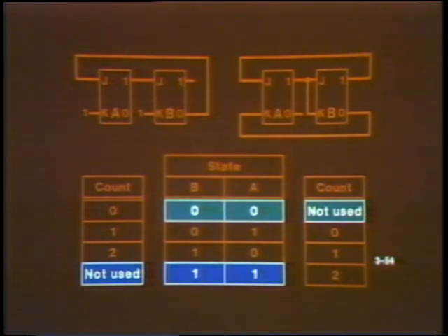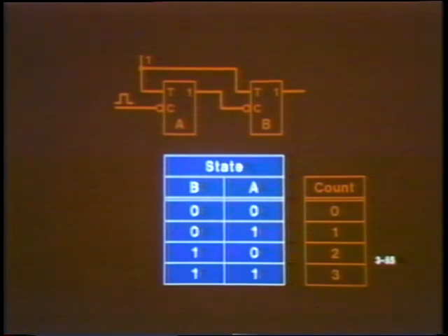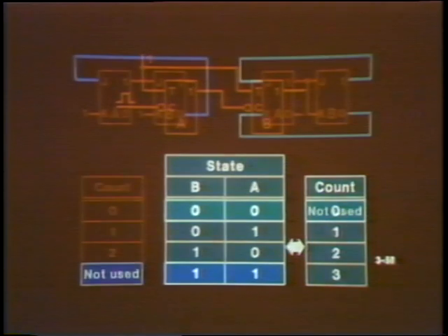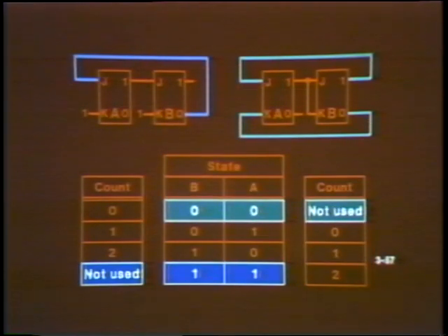In contrast, binary counters, like this one, use all possible states to represent numbers. Moreover, binary counters normally employ the natural counting sequence because it results in the simplest circuit. There is no reason to worry about feedback connections because they are not necessary. But with a non-binary counter, some of the states are not used, so the designer has somewhat more choice in deciding which states and what feedback connections to use.